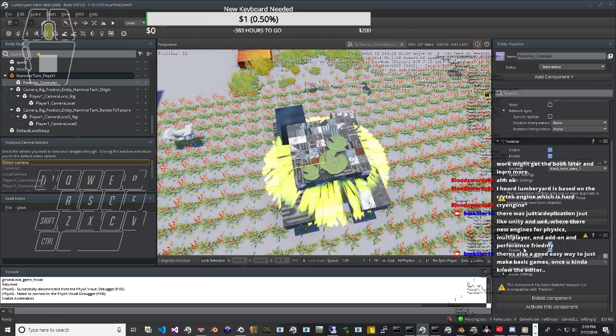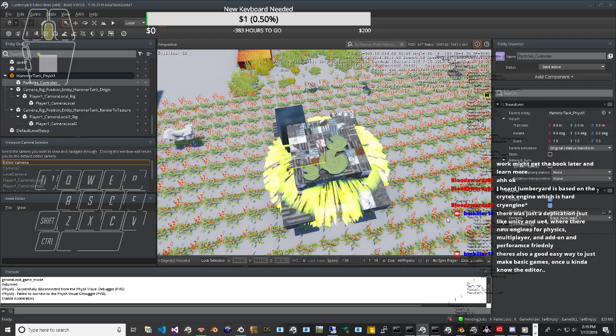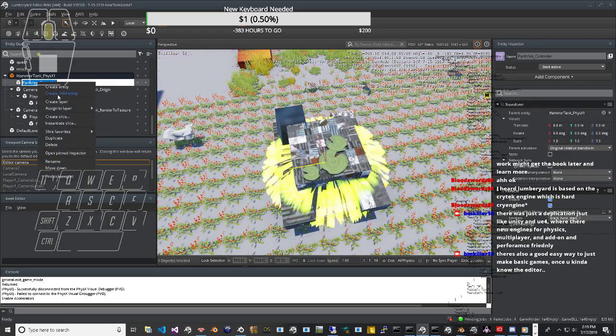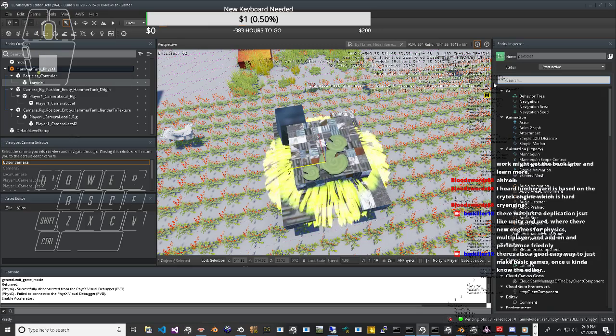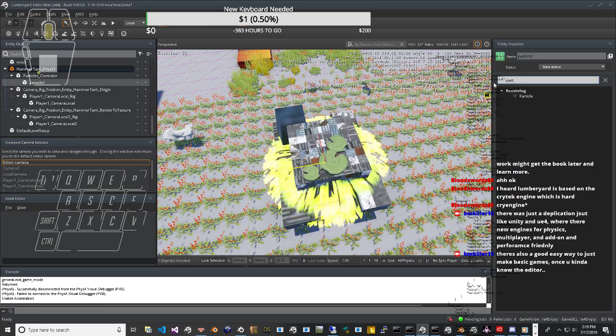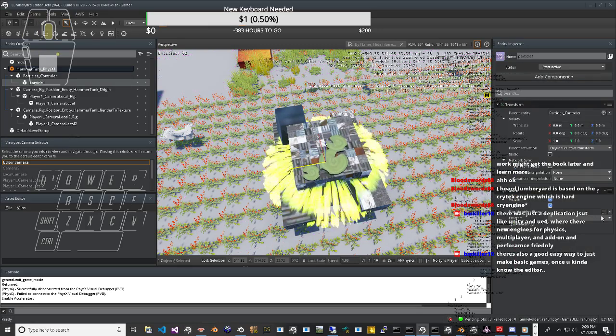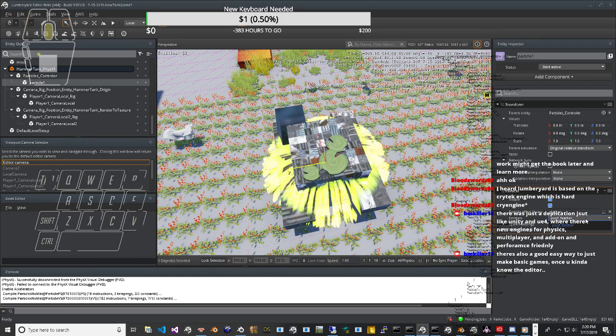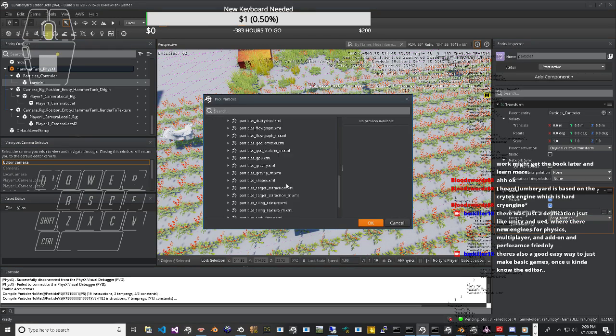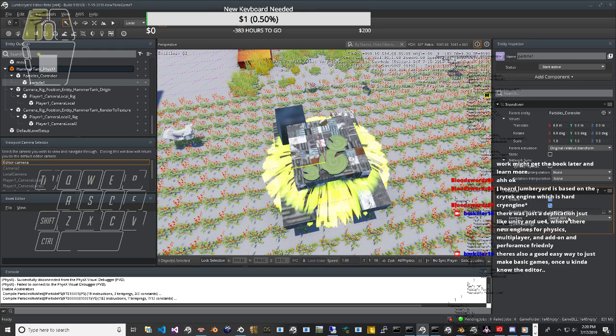Let's plot the whole formula. The horizontal axis measures S equals 100, which is really just slip in percent. The depth axis, going into the page, measures Fz from 5 kilonewtons, nearest us, to 0 in the back. The vertical axis measures the result of applying the formula to our model tire, so its longitudinal force of launching or braking. Notice that for a load of 5 kilonewtons, the model tire can generate almost 8 kilonewtons of force. Very sticky tire, as we've already noticed.